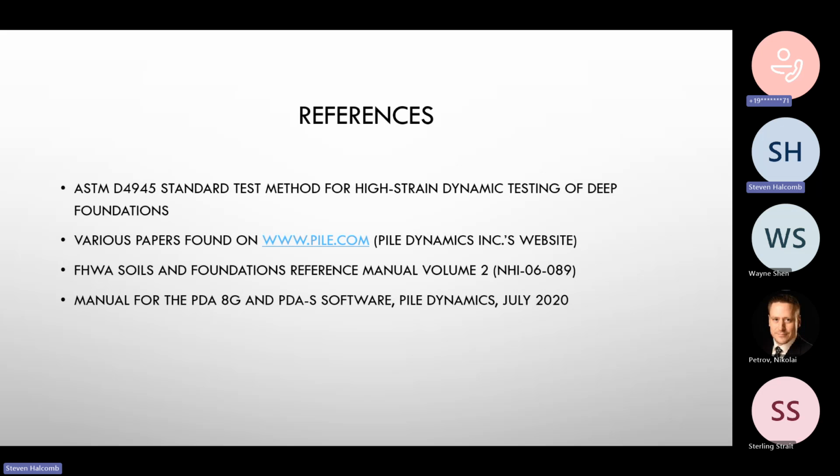You can look at the soils, and I get surprised all the time about how things are either way harder to drive or piles run. So it's definitely a difficult part of the job. And that's why we have these verification methods in the field, because you can't really trust these static formulas, empirical formulas, to predict capacity.